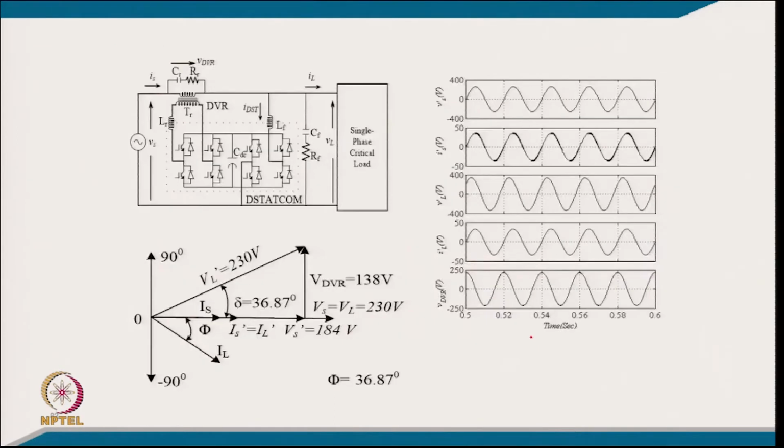across the load. So, this is the condition where voltage sag is applied, because it is a UPQC-Q. There was a voltage sag, the voltage is reduced from 230 volt to 184 volt, but that much voltage we have to inject as V DVR, and this is the new voltage. So, that is the concept of UPQC-Q. There is no reactive power down here. So, this complete model is developed, and then these are the performance results after the simulation.